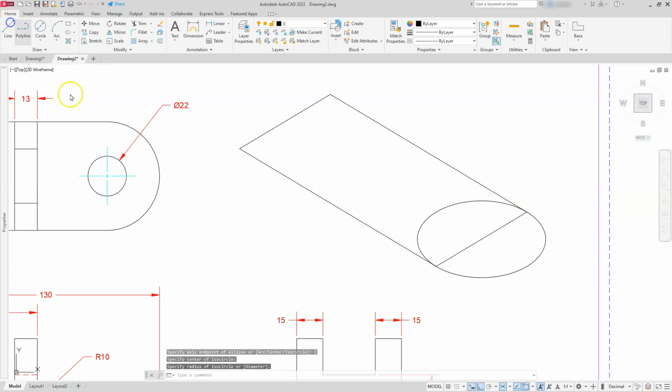Next, I'm going to create a line going from this midpoint out this direction. I would have tried to move that through any other means, but I need to get this intersection to be where that midpoint is, and this is the only way I can pull it off. If I try to grab any one of these quadrants, it won't move it in the right direction or to the right location. So let's go ahead and move this circle.